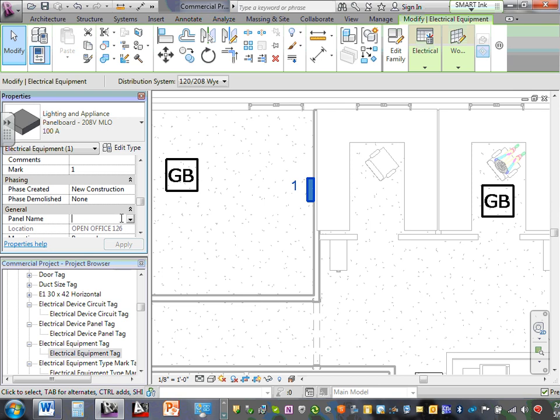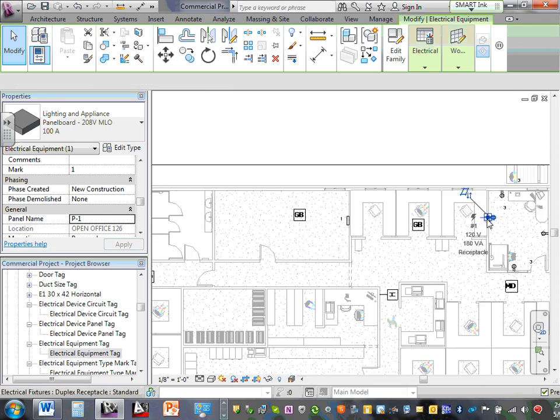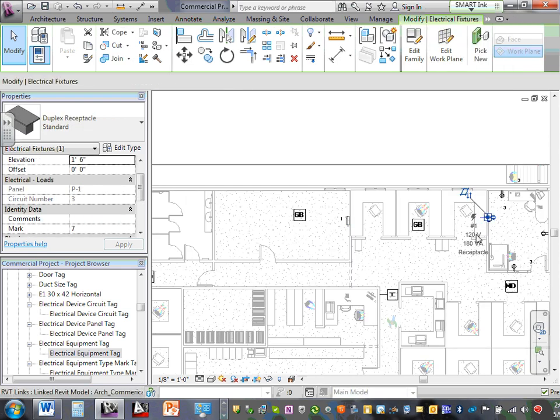Now click on your panel. Everybody's good? Good. Now do me a favor. Scroll all the way down until you see general panel name. Everybody's good with that? Go call it P-1. P-1. That's the name of my panel. Apply it. My panel name is P-1. Now go click on any receptacle that you circuited. Can you guys see that the name of the panel changed now into P-1? Right?